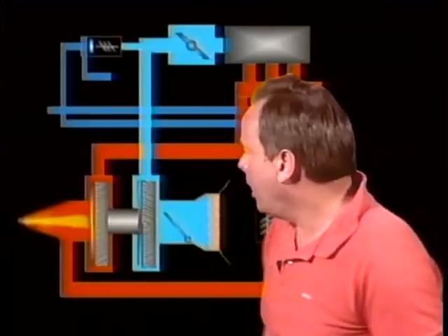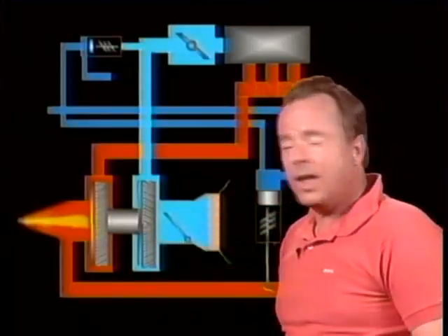They're going to say, all right, super mechanic, you shift from low impeller to high impeller during a ground check. How do you know it's working properly? Well, if it is working properly and this impeller speeds up, the manifold pressure would increase. And because you're doing a ground check and you're basically in a fixed pitch portion of the prop because the governor is not working because you're not at enough RPM, you would also have an increase in RPM.